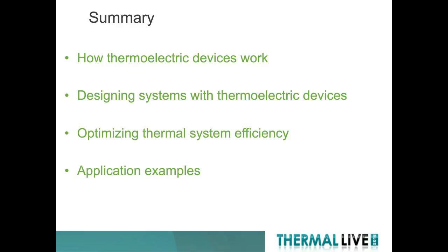So generally they are very robust devices. We do a lot of thermocycling testing, but some of the factors which can affect this is the device size. Generally, the larger the device is, the more warpage they can have, which can lead to defects.